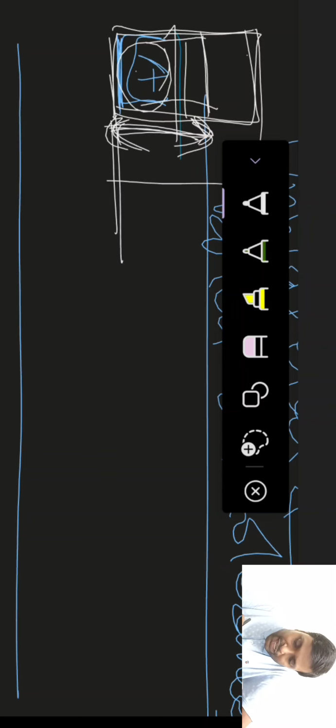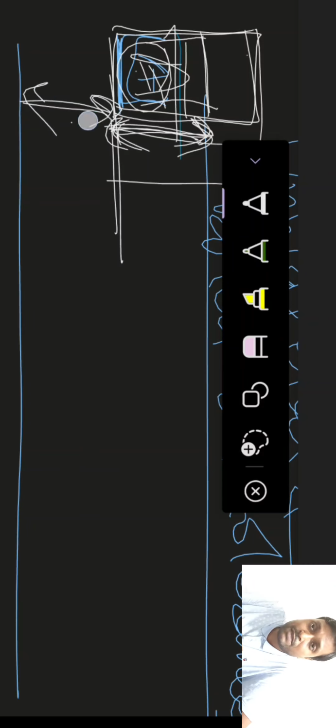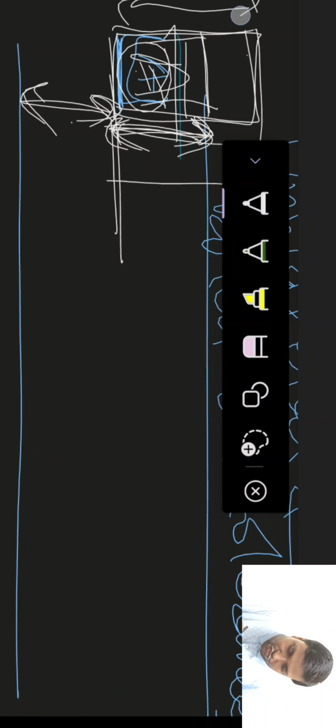Whenever we increase or decrease the tolerance, if the fundamental deviation is specified, letter A means the fundamental deviation is specified and this is its value, then the whole tolerance zone, or the variation, will be shown only on one side of the zero line.